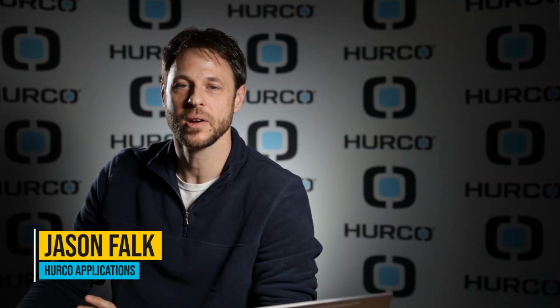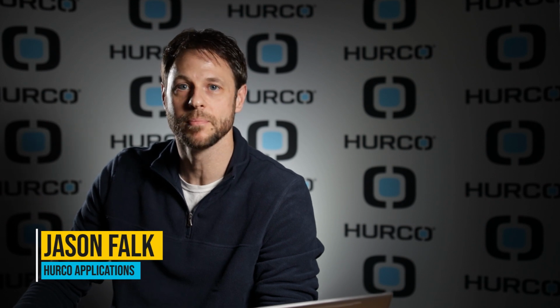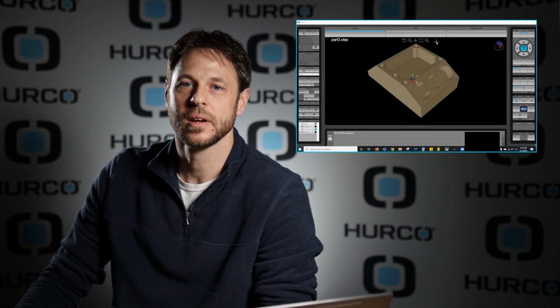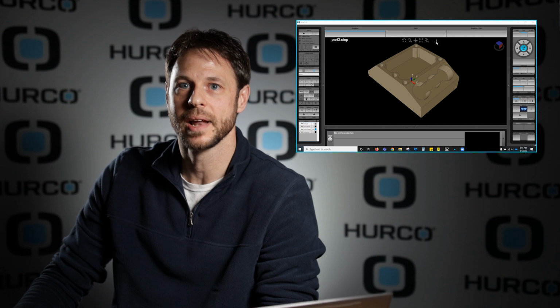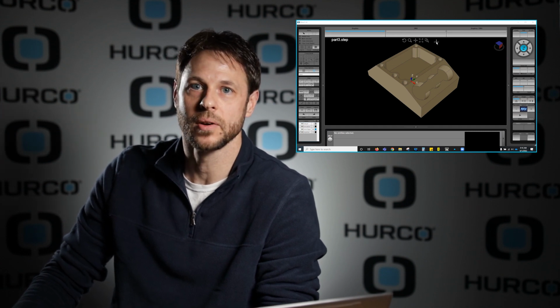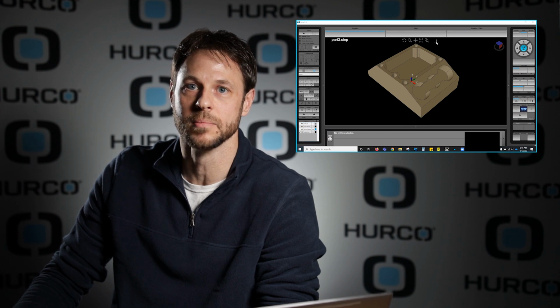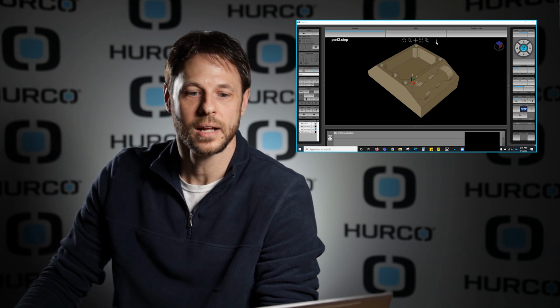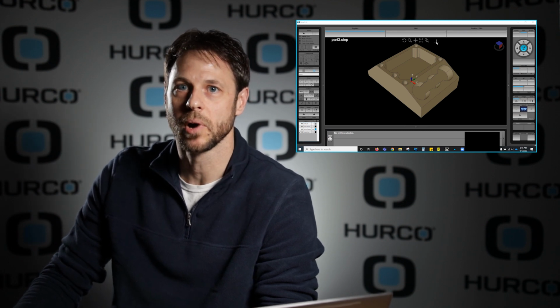Welcome to another video on Hurco's solid model import feature. In this video, we're going to go over a little bit more on how to move part zero and how to align your model with how you're going to fixture your part in the machine. So to start, let's go ahead and deal a little bit with moving part zero.